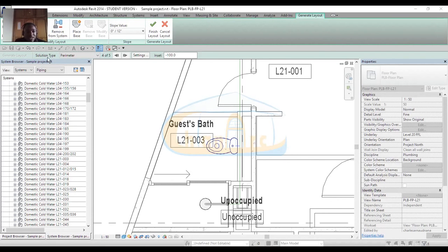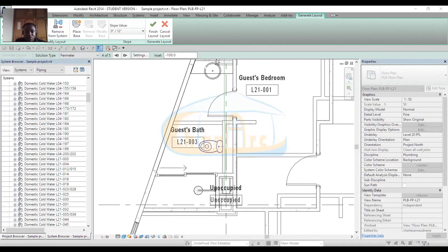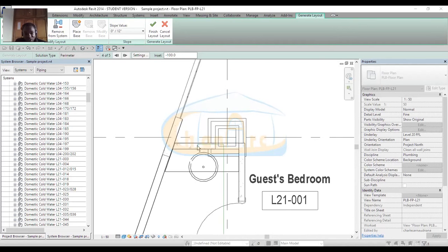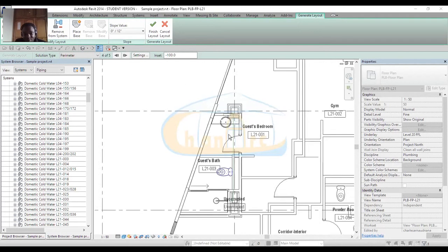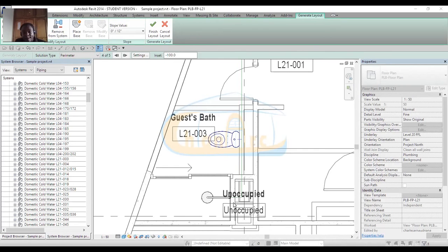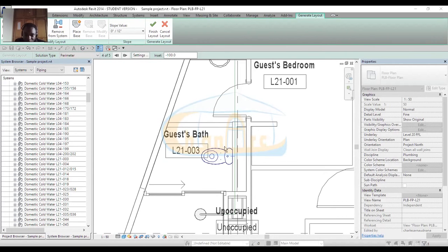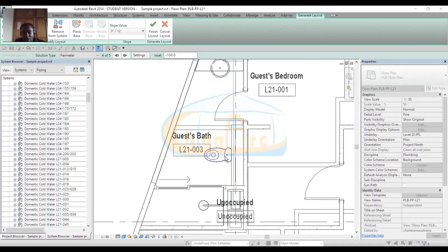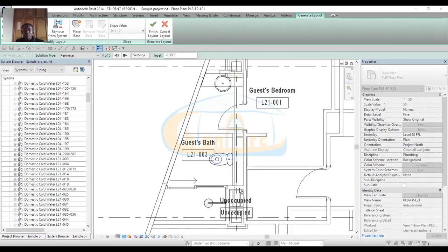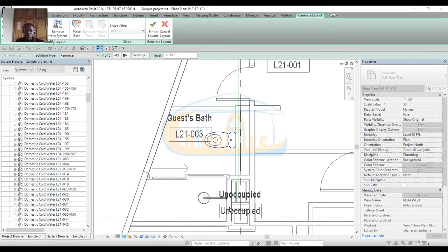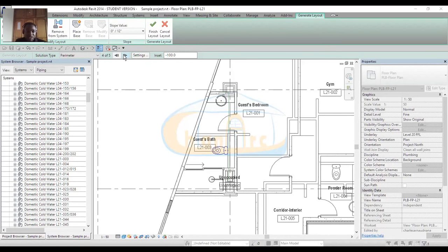The last solution type is the Intersection solution type, in which Revit would have some imaginary lines stretching out from the different fixtures perpendicularly to the connector. Then their probable meeting point will be where the piping is joining. In our case, it's not so workable because the plumbing connectors are not going in directions perpendicular to each other or meeting. So it is more or less trying to do some network connection type.